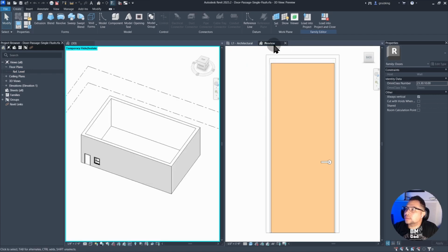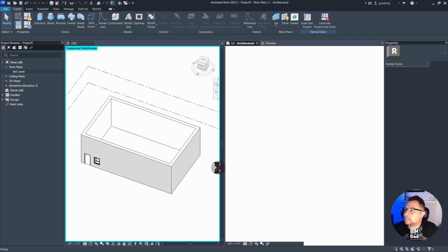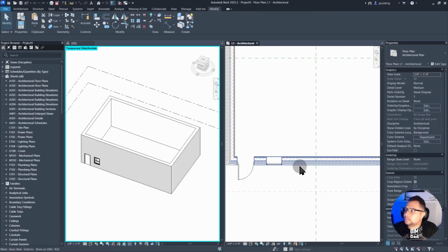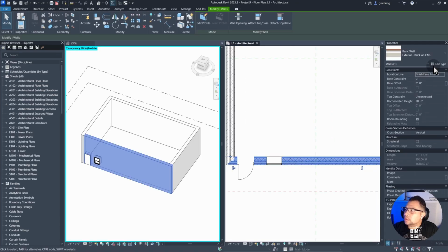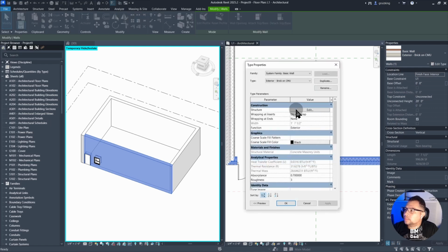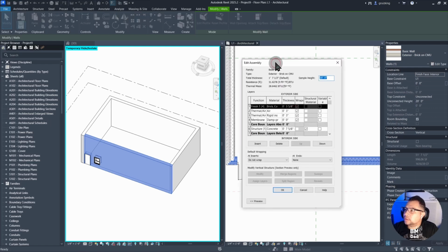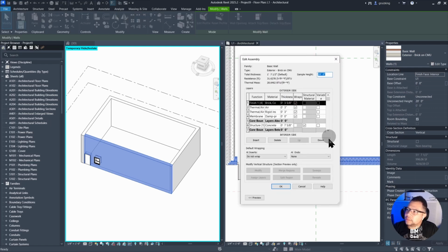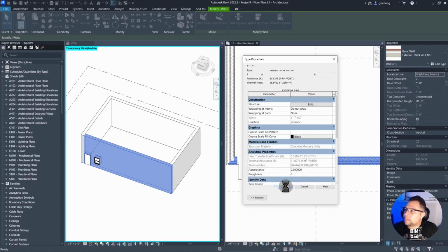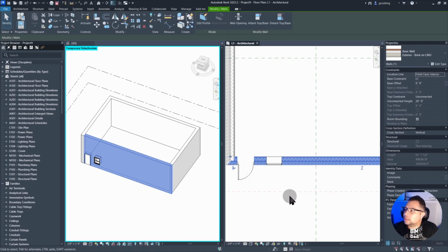And if I were to dig into the wall type, close that for a minute, and go to edit type for the wall, or edit structure, right? The exterior on this dialog is at the top, just like the family. And there's our brick layer, which is what we see here on the outermost. Hit OK here.